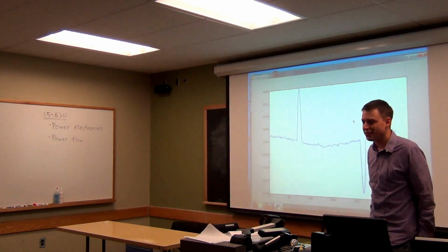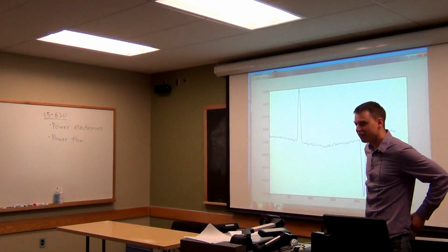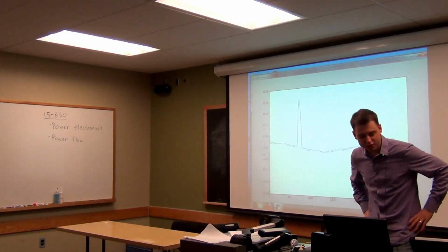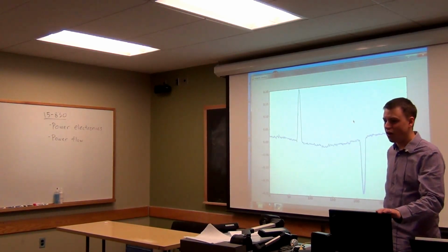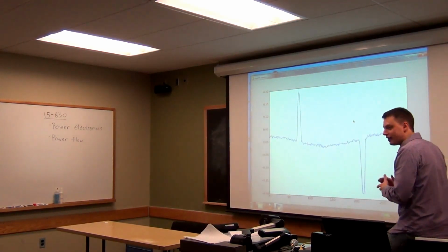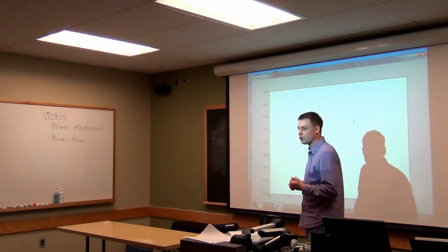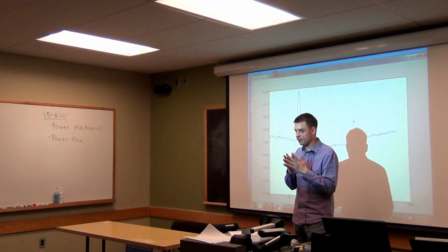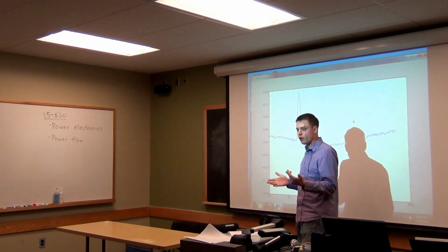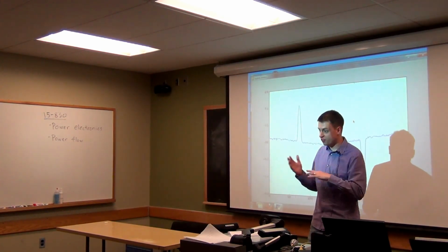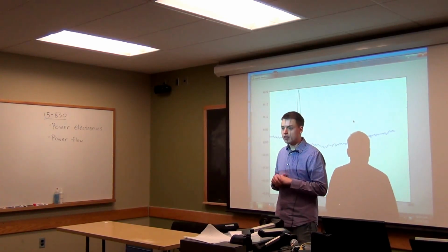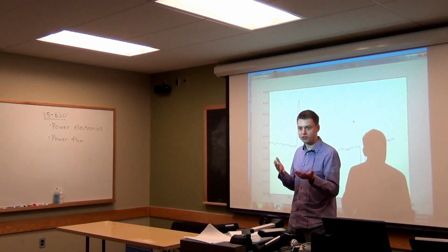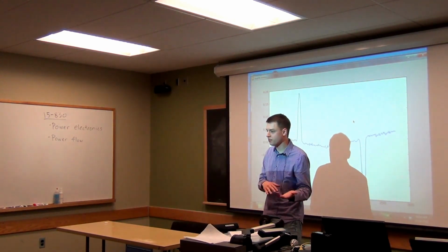All right, so again, what on earth is going on here? This looks nothing like what I expected to see when we talk about AC power. So what is actually happening? What's happening are nonlinear circuit elements. The reason why, even with sine waves, we call things linear, is that all that's really happening is you're shifting these sine waves around, changing their magnitude, and that kind of thing. And you can write these all as linear systems, because they preserve the sine wave: if you put in a sine wave, what comes out in the current is a sine wave too.